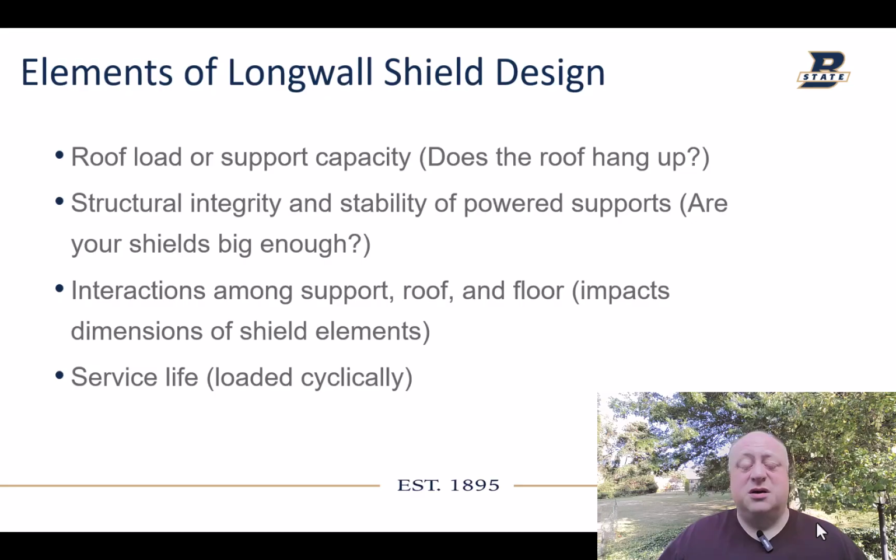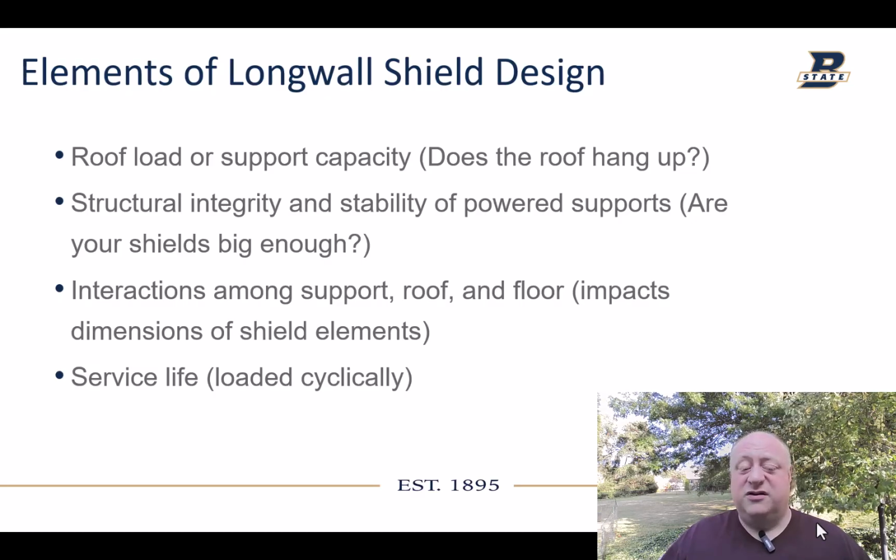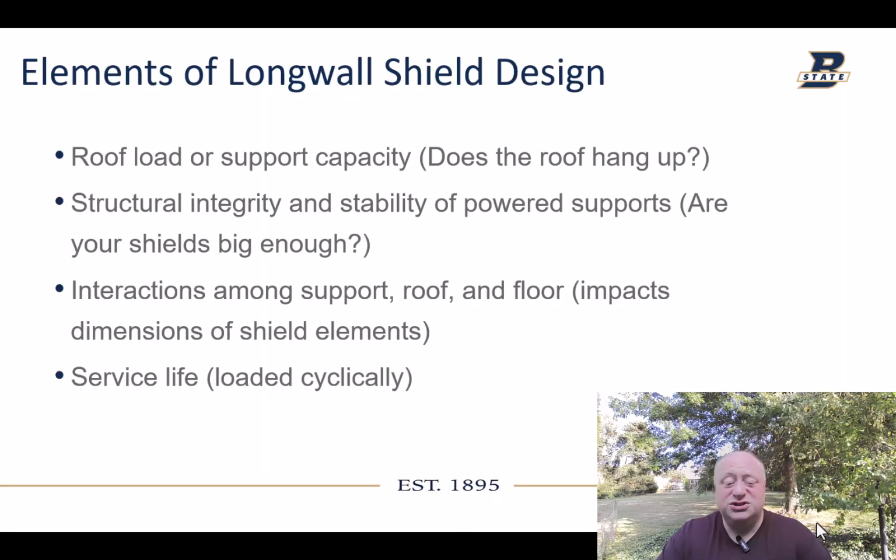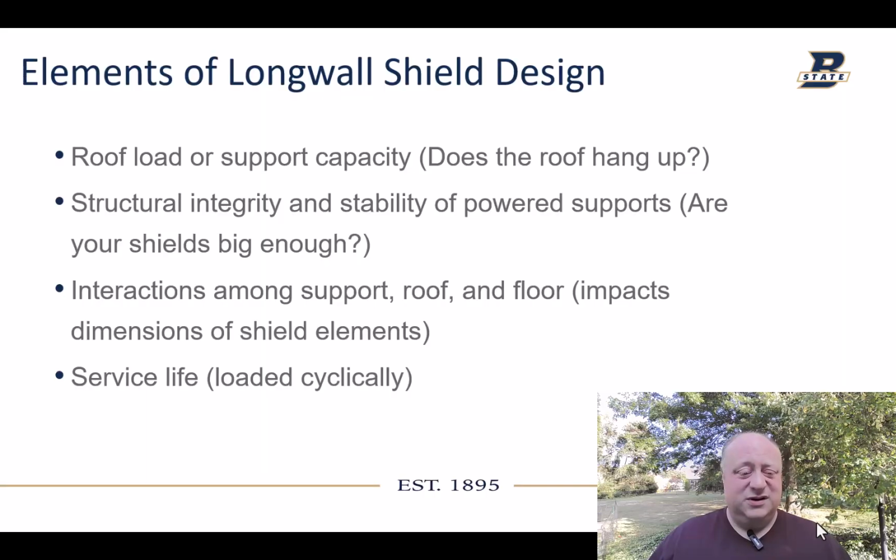Also, there are the interactions among the support, the roof, and the floor. This impacts the dimension of shield elements, and also it impacts the friction that's applied between the roof and the top canopy and the floor and the base, which does impact the resultant moments that act upon the shield. And then finally, you need to consider the service life, considering that shields are cyclically loaded, right? They have loading and unloading, repeated cycles of this over and over again, and they experience fatigue over time.